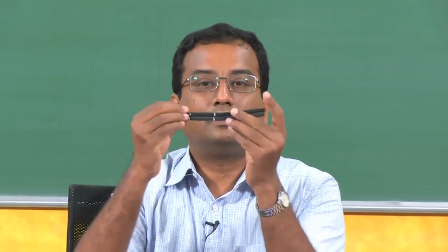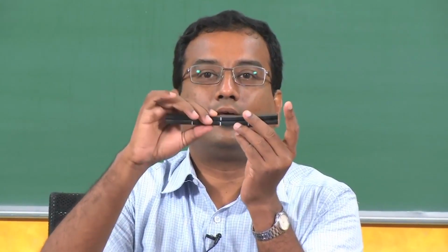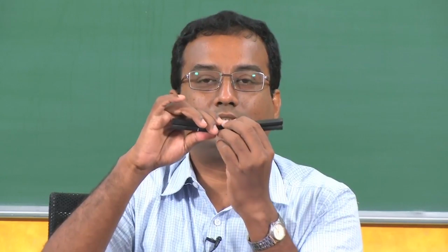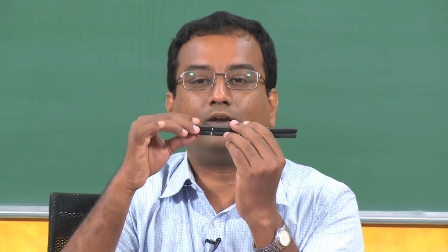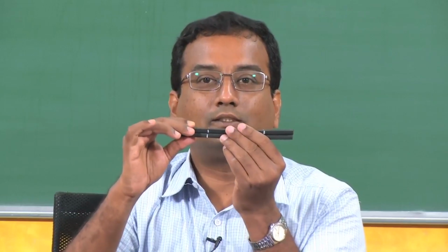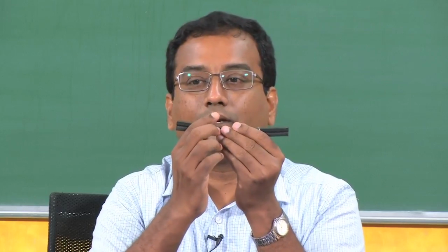This is because at this interface, since it has not been glued together, there is no mechanism to resist the shear stress that comes at that interface, and the shear stress is maximum at that interface because that will be the neutral axis of this cross section. So, basically because of this there is a jaggedness in the cross section. The assumption that we made in the analysis, that plane sections remain plane, is not holding good.